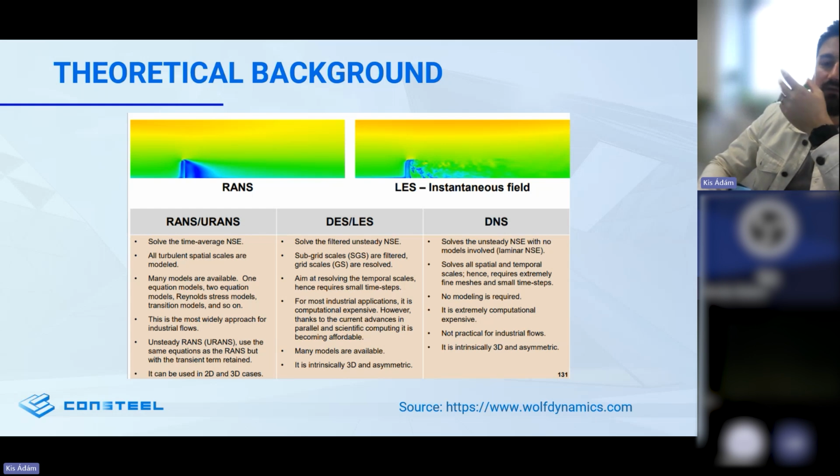Do we have to know all the streamlines and the accurate motion around the building? Because as you can see here at the left side, a result from the simplest Reynolds averaged Navier-Stokes method. And at the right side, we have this large eddy simulation, which captures these larger vortices and mimics the more realistic behavior of the airflow around the building. But again, for us, it is much more important to capture the pressure fields on the buildings.